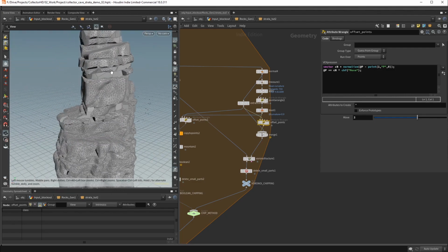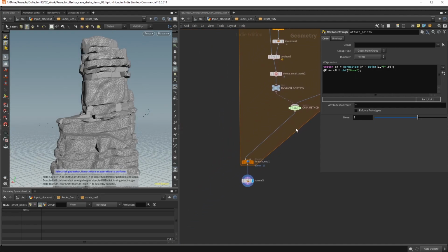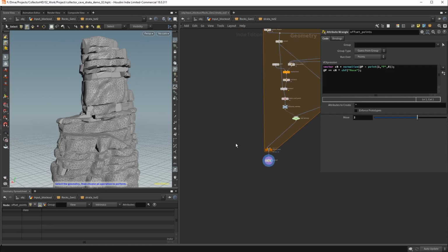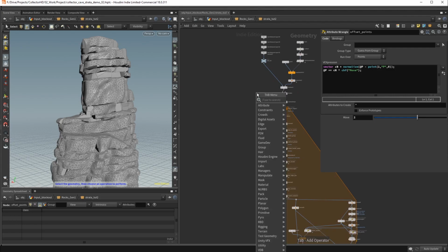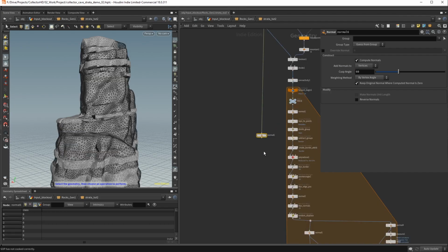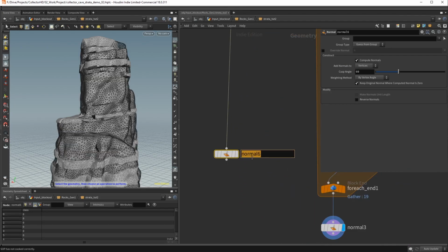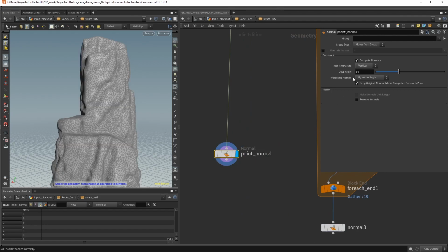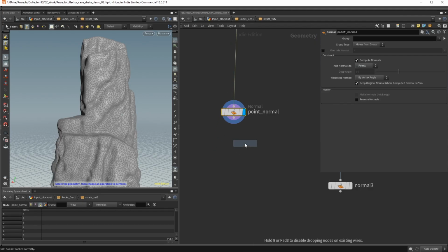And okay, so one last thing you can do to make your geometry watertight is to take the original input rock shape and scale it down a bit, and then just use the Boolean to union it with the new layer geometry. So it basically adds like a solid core to your new layers, just to be sure that there are no strange holes inside,